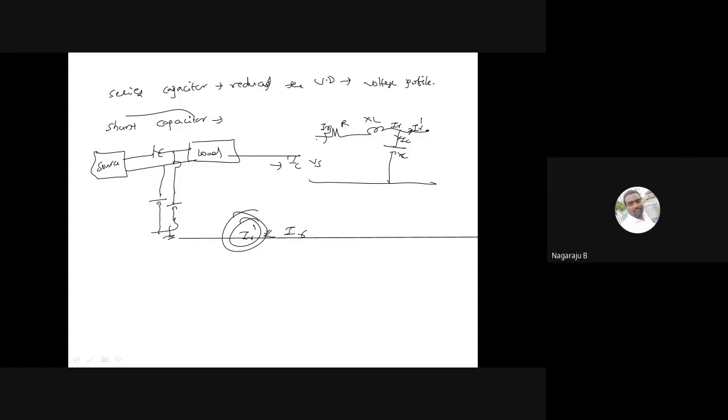A capacitor in series with the primary feeder serving a lagging power factor load will cause a rise in voltage, and the voltage on the load side of the series capacitor is raised above the source side, acting to improve the voltage regulation of the feeder.